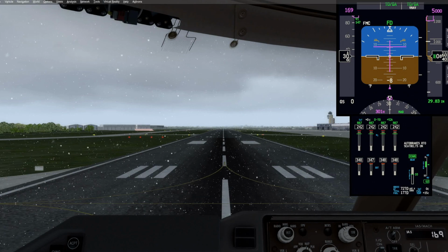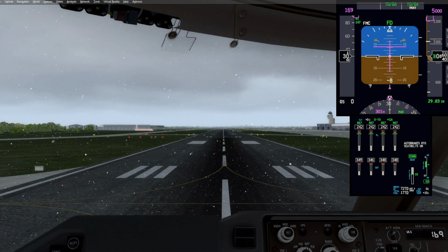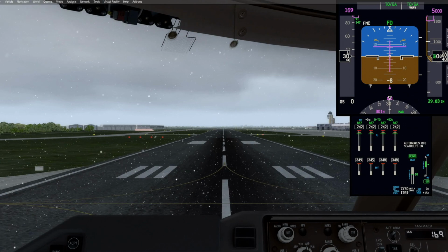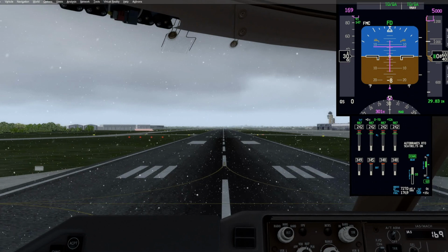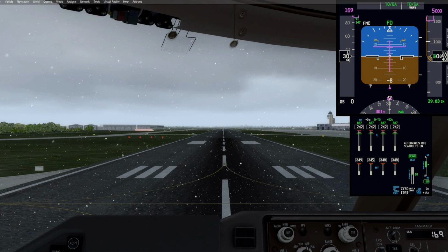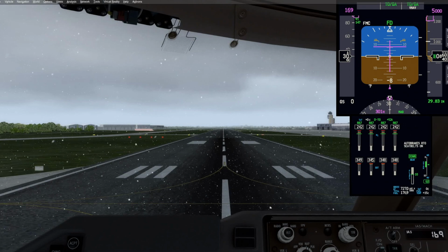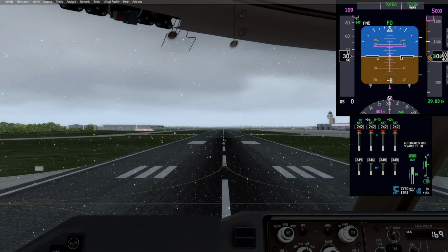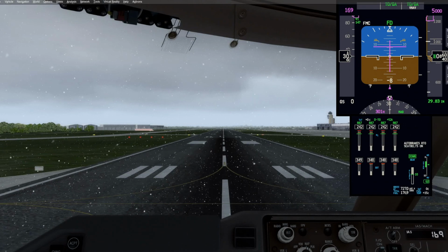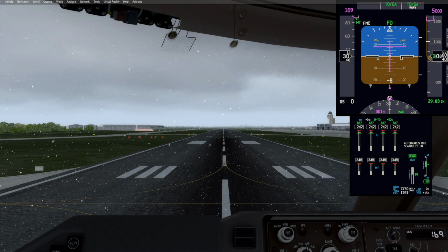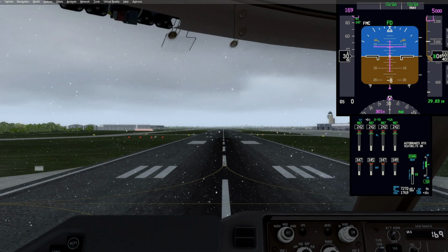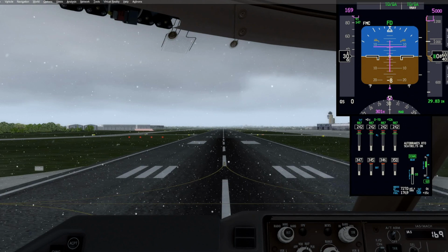With both of these, you shouldn't need to increase the thrust because your runway analysis charts, your dispatch papers, however your performance is figured, is predicated on the current weight, current conditions, current runway, and maintaining the segment climbs once you lift off. So what I'm going to demonstrate now is just taking off runway 30 left.